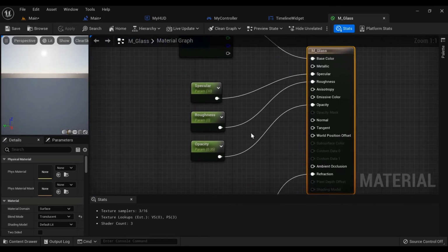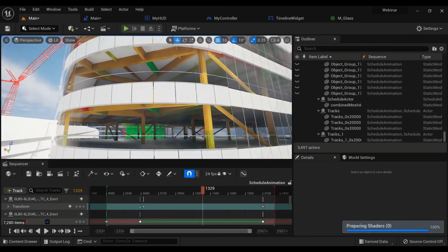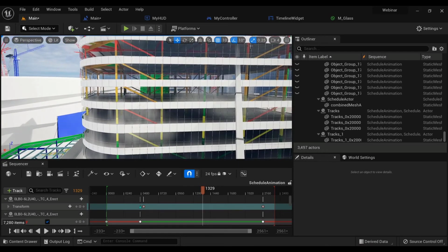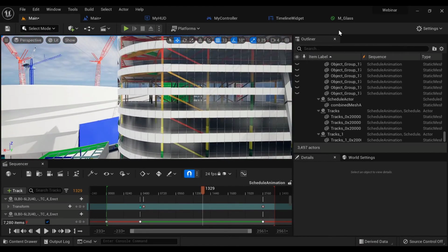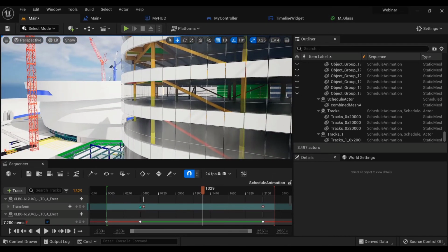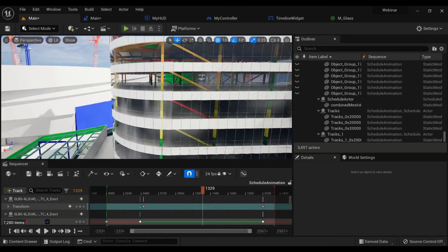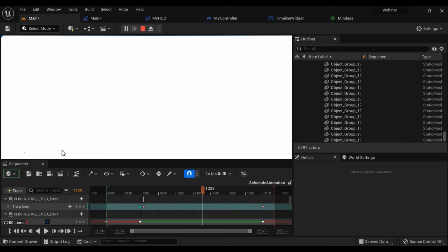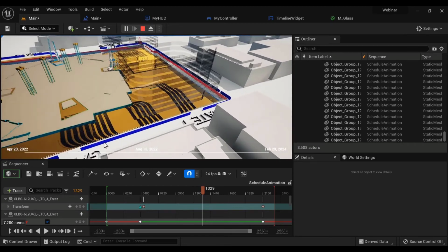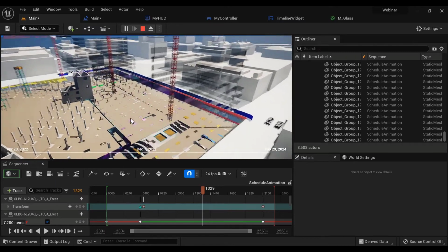Because the animation is shader driven when you are using the combined mesh, you actually need to opt into the visibility controls that the shader uses in any custom shaders that you apply. So that goes for our glass here because it has its own form of opacity, and really all materials do. They're all generally fully opaque, not transparent at all. When the clip plane animation occurs, you'll see the cutting plane. You'll see a number of issues by using the glass material, but it just is there. It's no longer hiding until its part in the animation comes up.